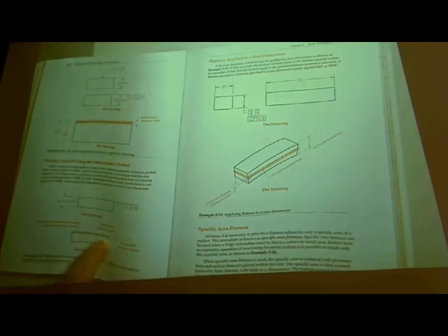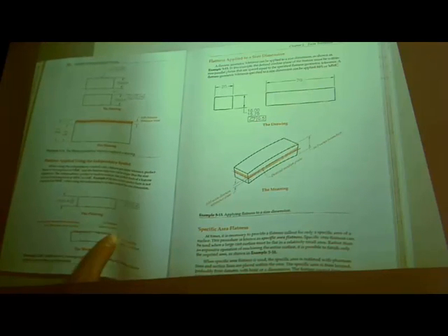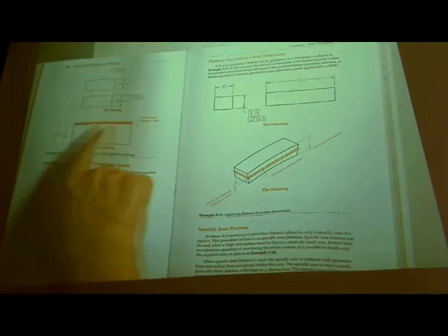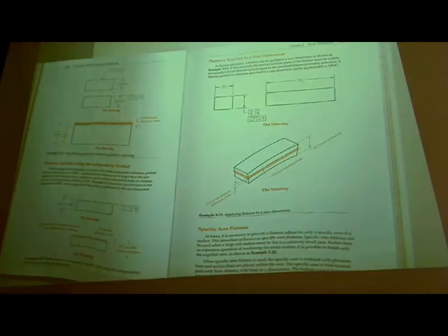I found it interesting they would use a curved part here for flatness, but a lot of times we're looking at flatness as an up and down mountainous terrain kind of thing that we're checking for, but it can also be just curved or like a sine wave as well. It can come in all kinds of shapes depending on how it's manufactured, but it's over the whole surface, but the geometric form is two parallel planes.